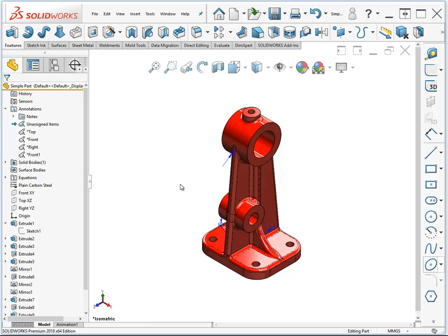I don't want to make any claims that apply across the board, but I can just tell you that personally, I apply reference dimensions to my drawing because I never am thinking about the drawing when I'm creating the 3D model. I'm just trying to get the most efficient 3D model that I can get. You may have heard also of model-based dimensioning, MBD, which is a separate module that SolidWorks sells for applying dimensions to the three-dimensional model in replacement of two-dimensional drawings.